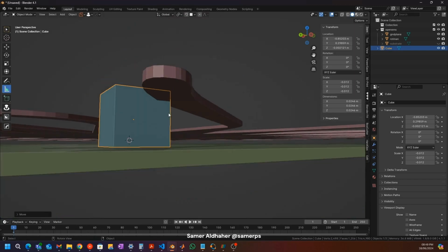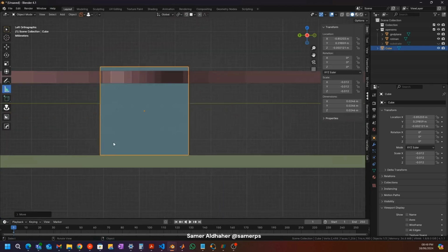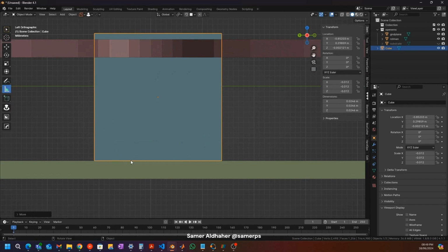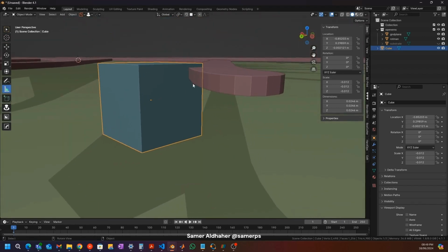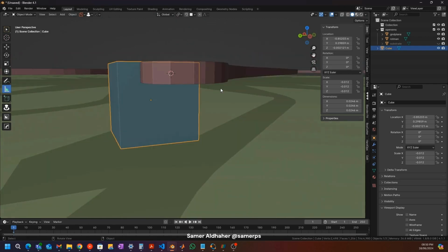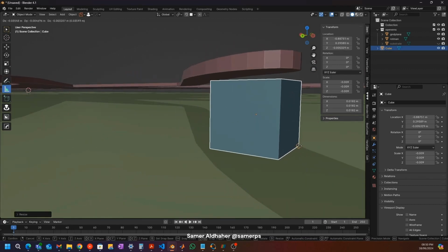Because when I do the meshing, since this is just a quick guide, the mesh line might not actually cut right at this exact point here. So it's best to have some overlap between the ports and the copper traces.